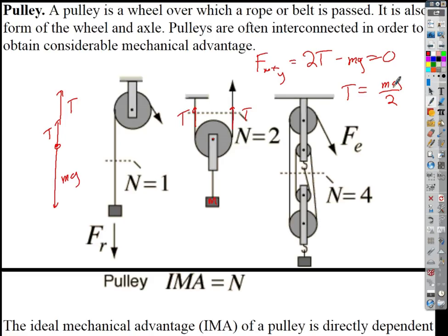Now, there's one disadvantage there. We didn't account for it. Twice as much rope. You have to pull twice as much rope, for sure. But something else is going on too. Do you see another practical disadvantage? Friction, sure, but even if we have a really good pulley with very low friction, there's still something else. Because we're not just picking up the load, what else are we picking up? The pulley. So we do have to carry the weight of the movable pulley also, right? But that could be relatively small.